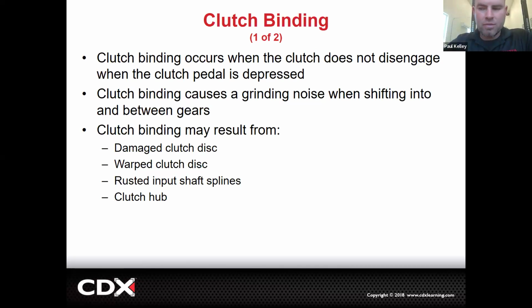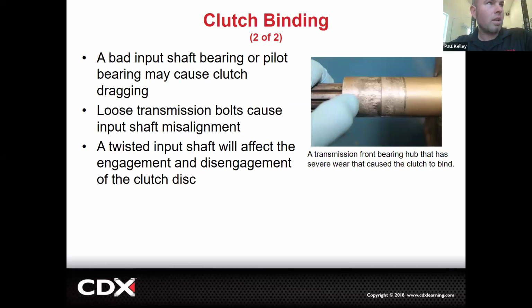It's kind of like brakes. If you do a good brake job, you're not going to have these issues. If it has these issues, you're kind of just selling a good brake job. Even if the pads have been done recently, it's like, hey, we need to redo this. You didn't cut the rotors. You didn't lubricate the right points. You didn't clean the right areas from rust. It's that type of thing. Just doing the job well is going to eliminate a lot of this. Like this, however, would need to be replaced. This is that clutch sleeve or that hub right there. So that one would be no go.